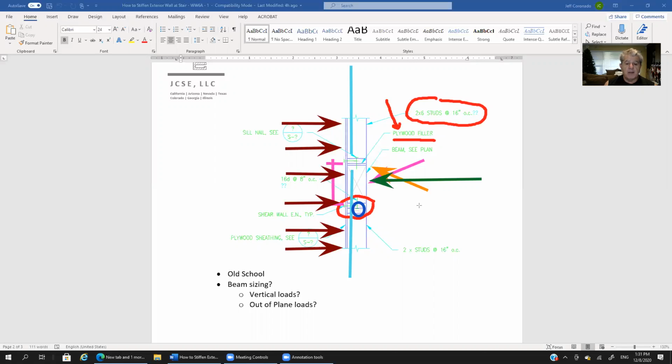Keep that in mind. Now all of a sudden this beam is not acting about its strong axis, it's bending about its weak axis. So you're designing a beam for weak axis bending. If you need help with that, I believe there's another tutorial on bridging the gap that will help you with that. But you need to resist the pressure here in weak axis bending due to the wind component and cladding pressure.